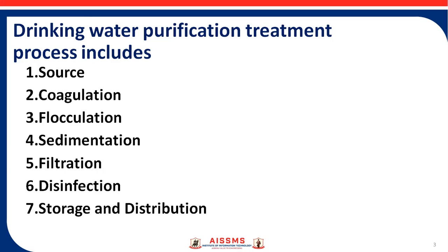Next step is disinfection. The process to protect against bacteria, viruses, and other microbes. The water must be disinfected. The killing of harmful bacteria with the help of chemicals or substances is called disinfection, and chemicals used are called disinfectants. Examples of disinfectants are hydrogen peroxide, sodium hypochlorite, phenyl, etc.